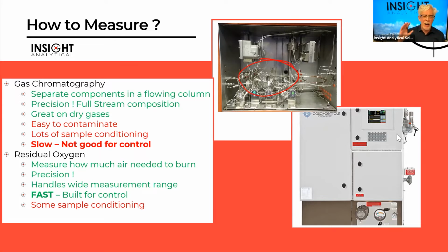A typical chromatograph will take several minutes in order to do analysis. So it's not suitable for a process control application, not for something where we're looking like a burner that, we can have very fast changes in fuel compositions.